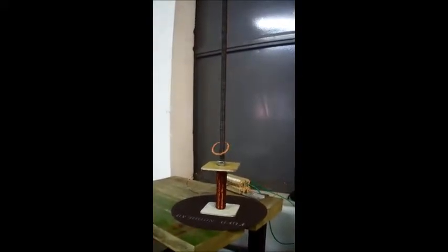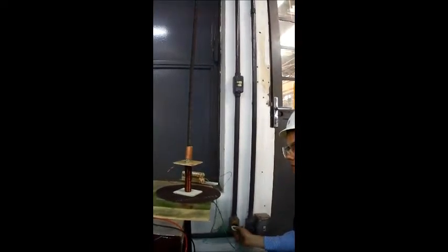When a varying current is applied on the coil, a varying magnetic field is produced. This magnetic field induces a voltage on the secondary, and consequently a high short-circuit current flows on the ring. By Lenz's law, this current has a direction that creates a field opposed to the field generated by the coil.